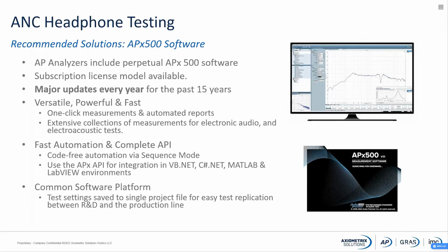So then you can share all your projects and all your automations with other APX units anywhere in the world. And we are basically offering a lot of solutions for electroacoustical testing, both for R&D and production. You can do perceptual audio testing like POLQA and PESQ, speech intelligibility, and most common electronic audio measurements out there.